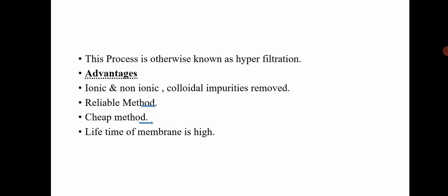After studying this reverse osmosis technique, students will be able to understand the water quality parameters like improved taste and odor, reduced total dissolved solids, removed contaminants, reduced heavy metals, and the environmental outcomes of using these RO systems. By using RO systems, we can recover up to 50% of wastewater. It eliminates the need for chemicals in water treatment, and the concentrated waste can be disposed of properly.